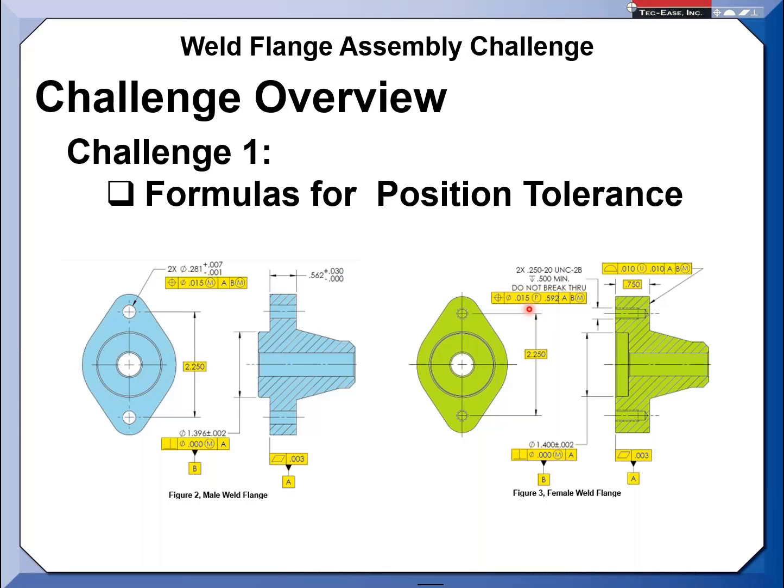The downside about threads is that since it's a V-type geometry, as I torque the fastener, it will self-center the bolt to the threaded hole. So it's not like you do get that additional tolerance. The bolt will shift all one way unless you forcibly hold it up against there.